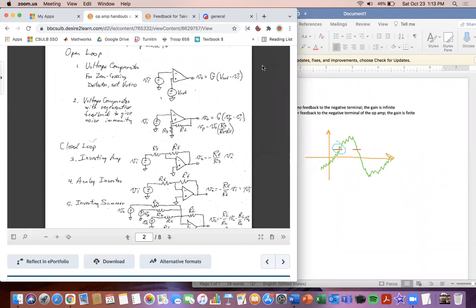We'll notice when we blow this up, so I have it right here and I have my green sine wave, it will go through and intersect it 1, 2, 3 times. If we just take a zoomed in portion, 3, oh, maybe 4 here. So we can see it intersects 4 times. So what we do with this is we give it noise immunity since we're able to change the reference position. So if it intersects once here, then the reference would change and go down here.